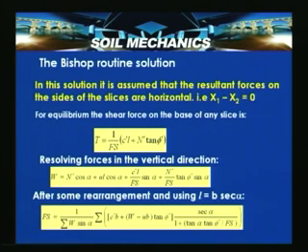So, manual calculations are difficult here, but manual calculations are possible for Fellenius method of slices, even if the soil strata has up to 5 soil layers. But for Bishop's routine solution, considering the involvement of iterations, a computer program is recommended.